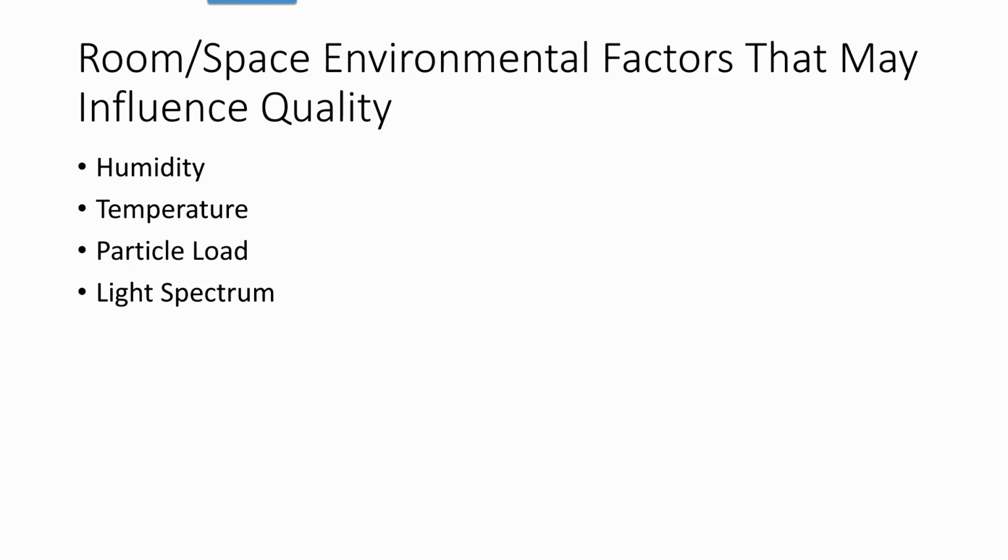For example, if temperature doesn't really have any impact on your product quality, say it's perfectly stable even if it was warm in the room, you might still have a comfort level, obviously, a temperature maximum or temperature range on your room, just for comfort purposes. Personnel, you don't want them sweating or possibly contaminating the product that way. So even if there is no environmental factor that would influence the product quality, there may be other things.